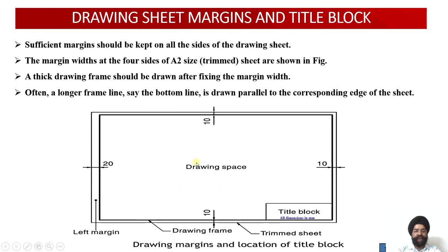In an industrial drawing, I am going to write the part number, the name of the component, the method of projection, the tolerances, materials, and the scale. I am also going to write who has checked the drawing, who has prepared it, who has finally verified and approved it. All this information will be coming in this title block.